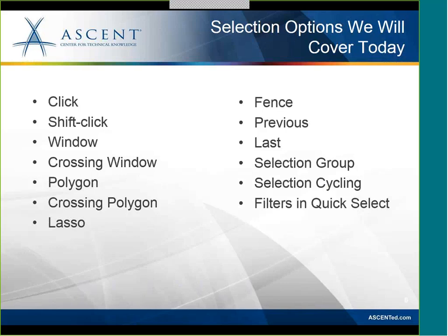So Norman says fence is great. Thank you, Norman. How many of you actually use Quick Select? Have any of you used that? I personally love Quick Select. It's a great way to select just the items that you need, maybe on a specific layer or any that are a specific diameter, circles and stuff like that. There's all kinds of ways to use Quick Select. So I'm going to show you Quick Select today. And then we actually had someone that mentioned that they use the Select Similar. So those are all the topics that we're going to be covering today.